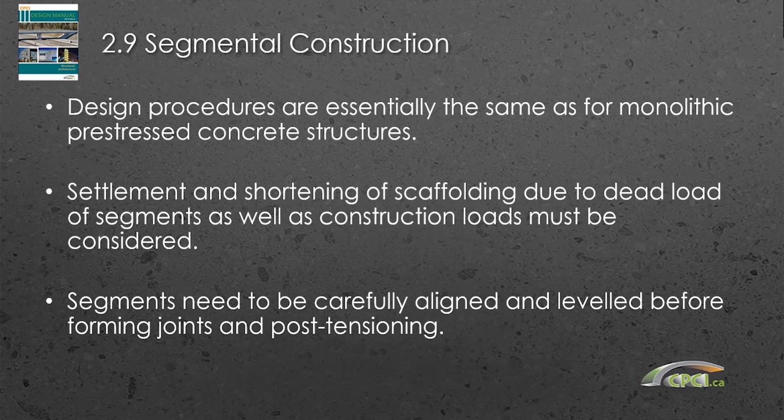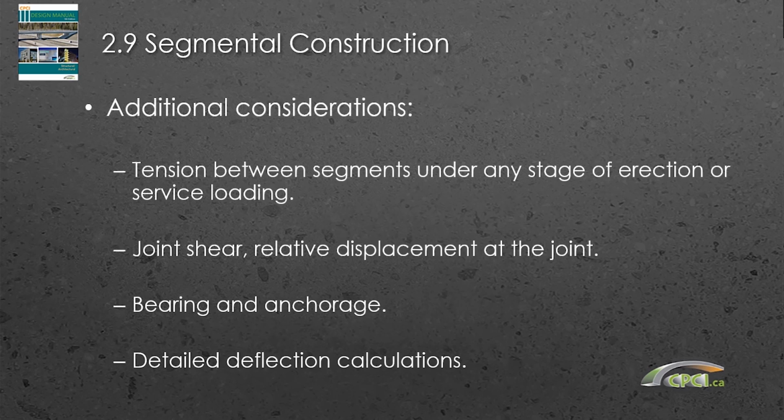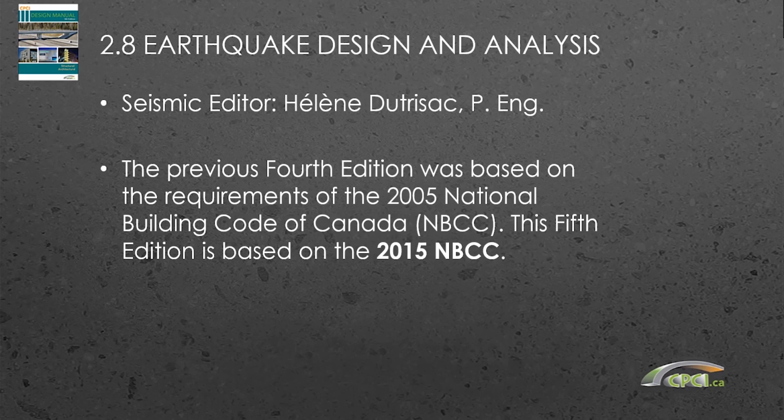due to dead load. Segments need to be carefully aligned and leveled before you do the post-tensioning, and you really need to look at additional items such as the tension between segments, the joint shear, relative displacement at joints. Very important to look at post-tension bearing and anchorage to make sure you're not getting cracking or high tension stresses, and that you're following proper reinforcement details in the anchorage zones, and really need to be careful looking at deflections. So again, Chapter 2, Section 9 has some information about segmental construction.